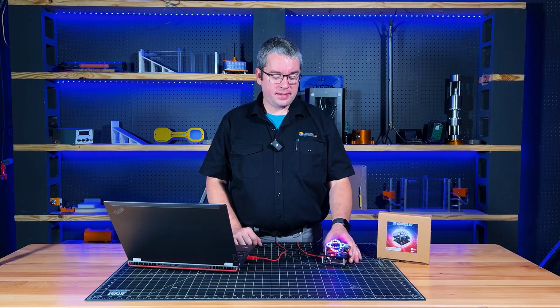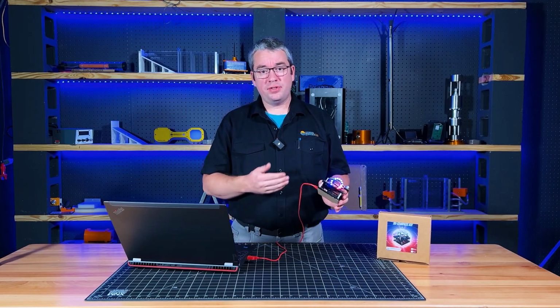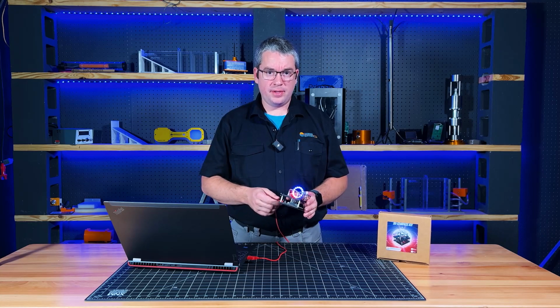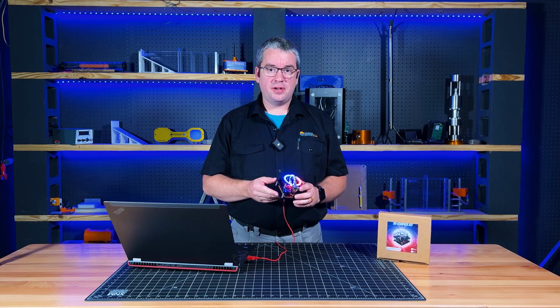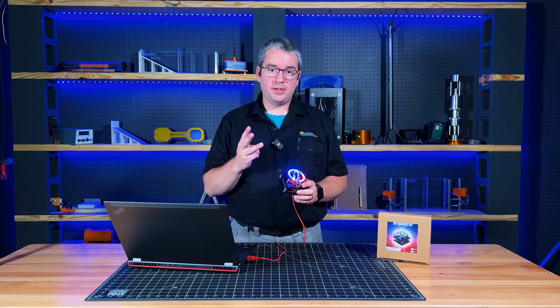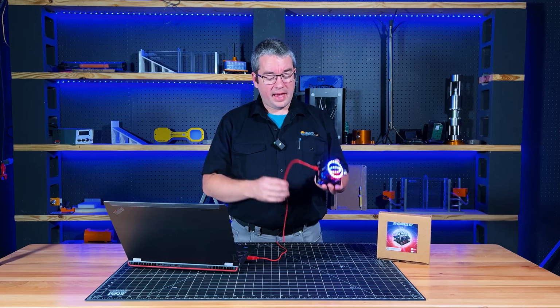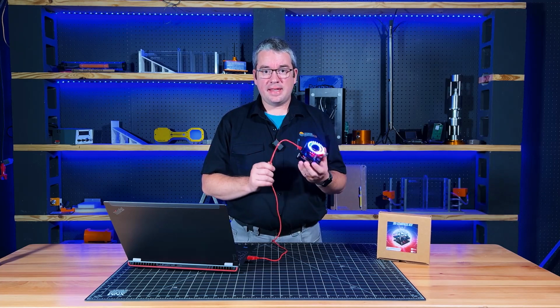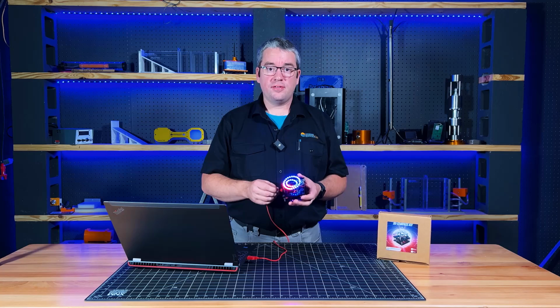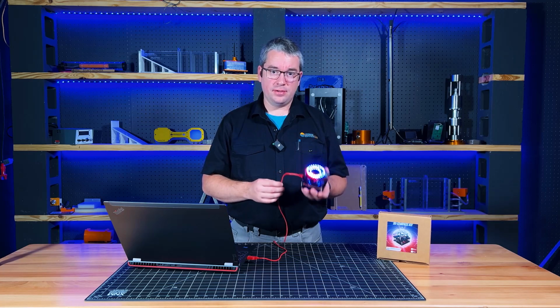Today I'm going to show you how to take your 3D compass and pull data off of it using a serial terminal program on your computer. The magnetometer on the compass measures three-dimensional magnetic field, X, Y, and Z. So out of the USB cable, we're actually sending that data to the computer via 115,200 baud serial connection.